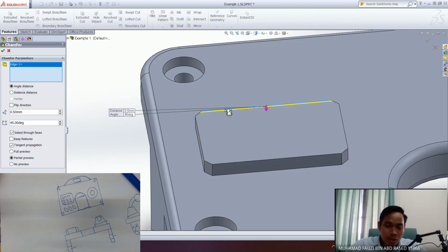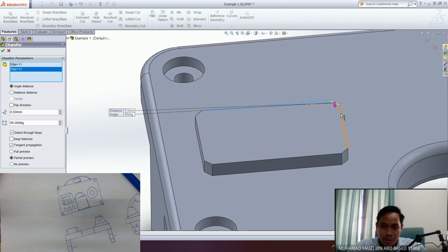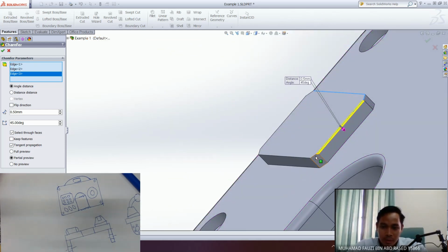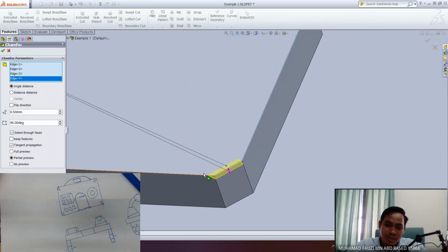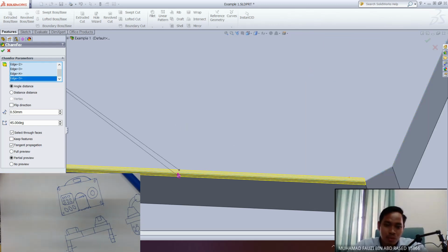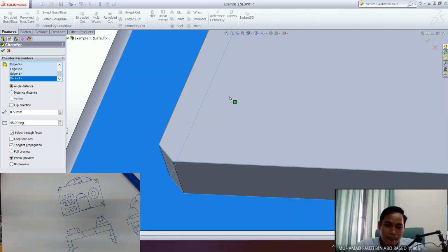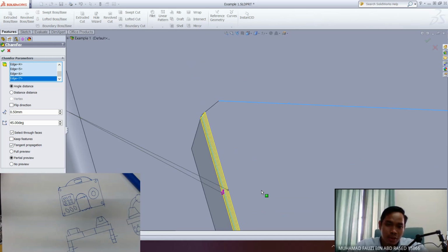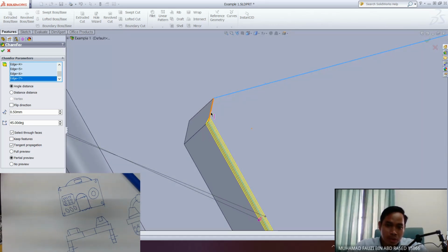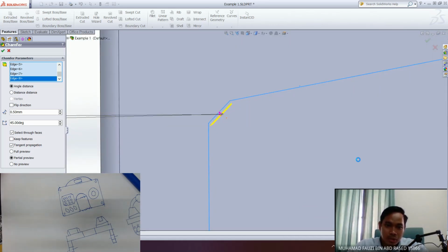It's different: whenever you select chamfer for a solid, in the feature tab, you can make multiple selection, and it also will show you a preview of how the chamfer will look. As you can see here, I mistakenly selected, so just delete that selection and make sure you select the proper edge. Then just click OK.